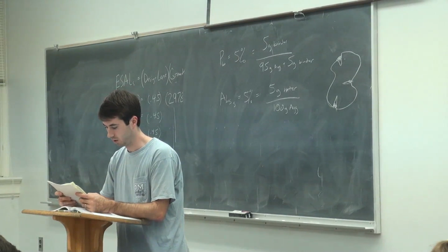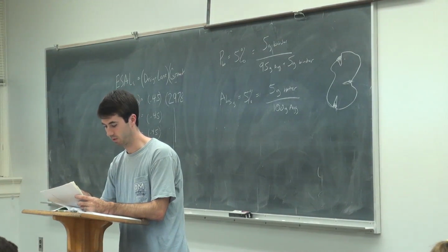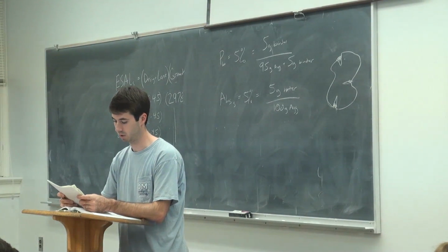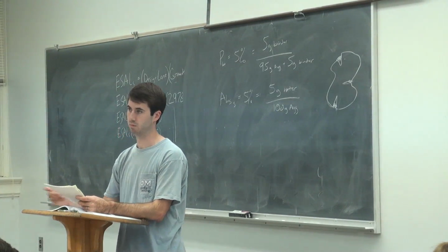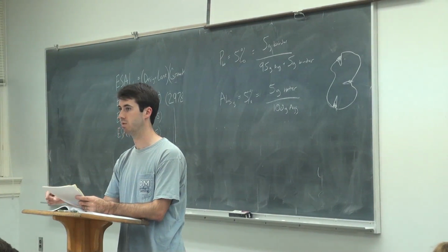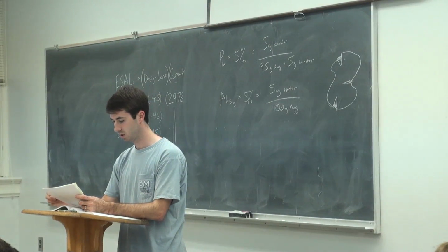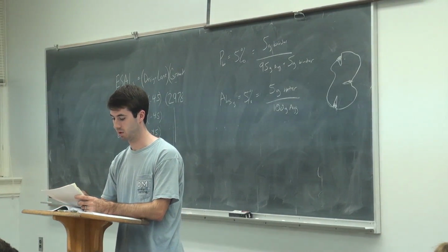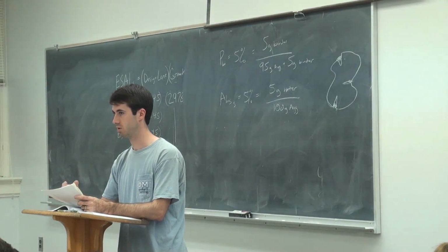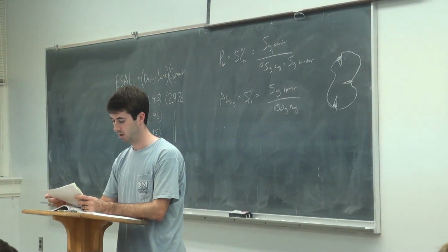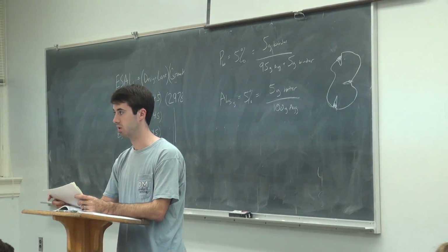And then they do the rolling thin film oven, same exact thing, except now your criteria is 2.2 kPa, because now you've aged it some in the thin film oven, so you'd expect it to be stiffer. So now, at the same temperature, they're allowing the criteria, the maximum, to be stiffer. That's how you get your high-end number.